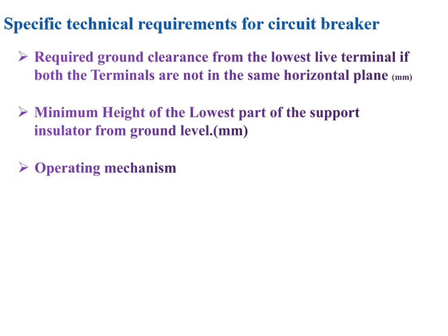There are spring type operating mechanisms, there are motorized operating mechanisms, there are pneumatic operating mechanisms. So depending on your convenience, your requirement, and your speed of operation, you have to decide the operating mechanism. That can be spring operated, motor operated, or pneumatically operated.